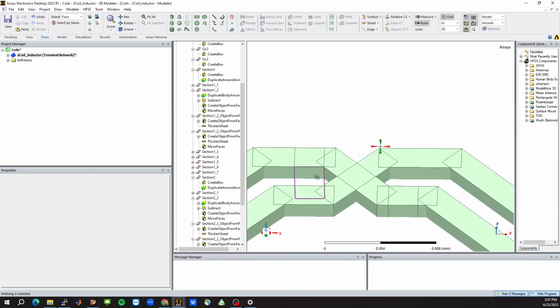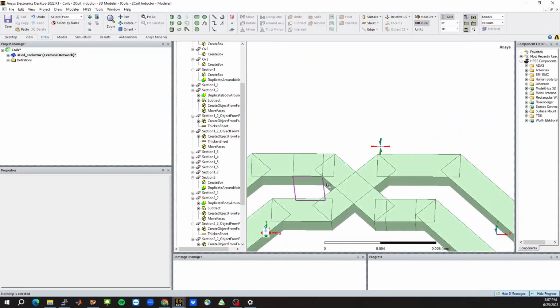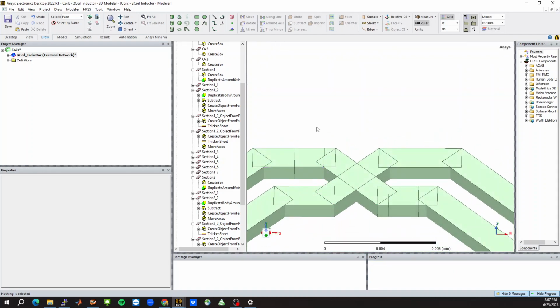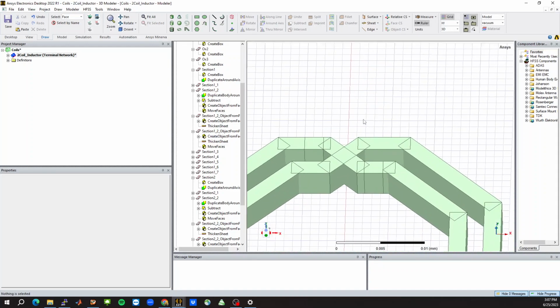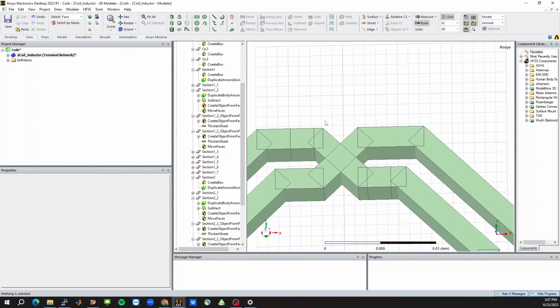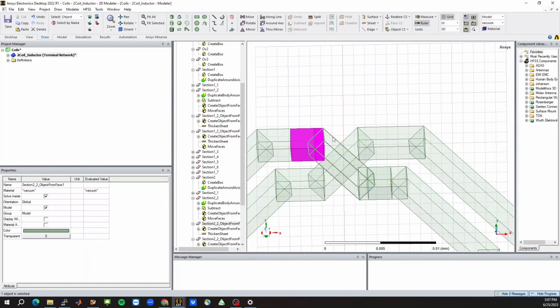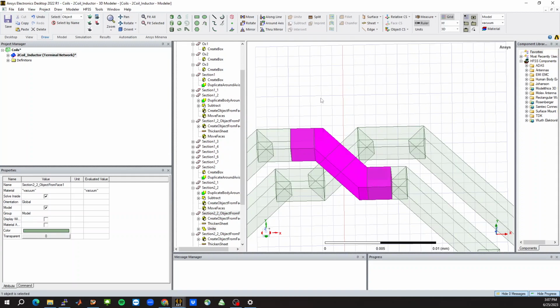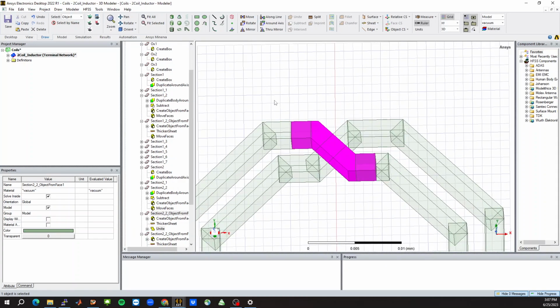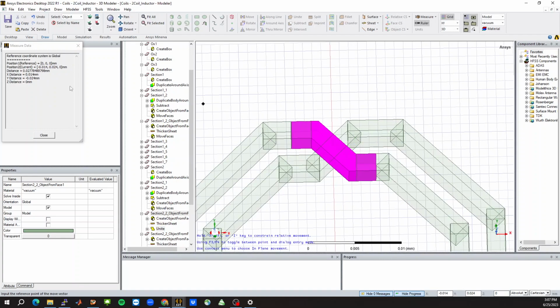All right. Now again, select all the objects, come up here. Okay, so now what do we have? We have this section, and this section. So you want to unite these, and then let's move this up. The way to do that is you right click, edit, arrange, move, and now it's in this mode.